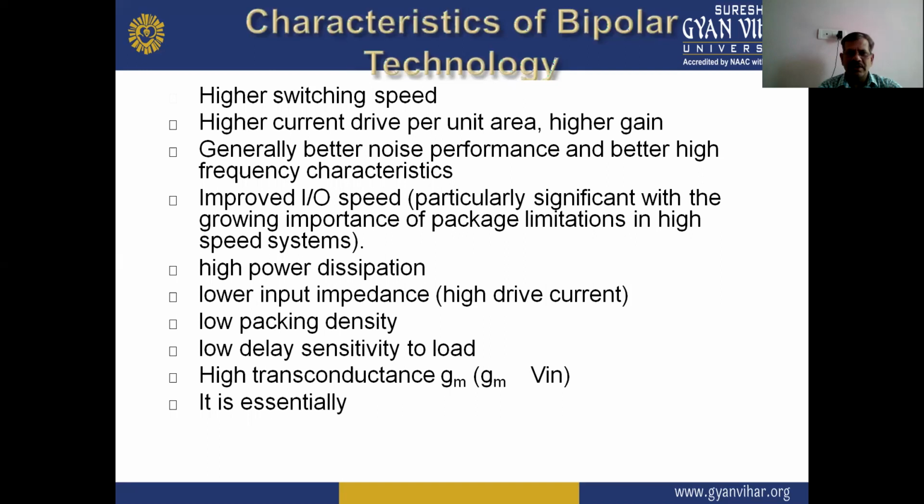input output speed, particularly significant with the growing importance of package limitations in high speed systems, and also high power dissipation in bipolar technology, lower input impedance, high drive current, low packing density, low delay sensitivity to load, high transconductance gm. So these are some characteristics of bipolar technology.